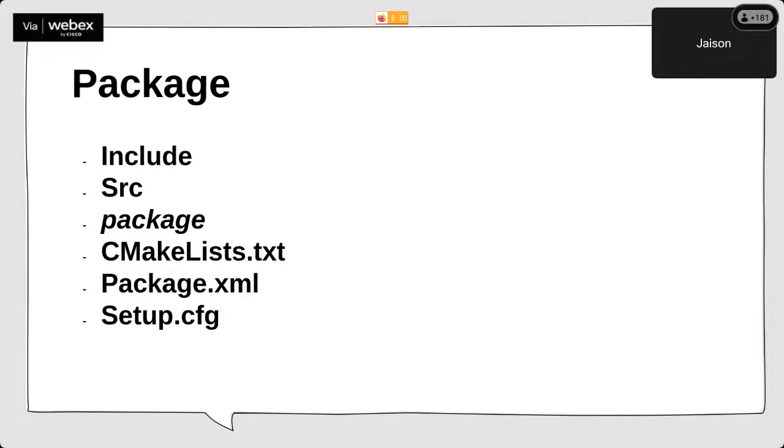So in the SRC folder, you will have all the Python files or the C++ files of how to detect a fruit and all. Then there is also a package. So package will be that same. If you have created a package named perception, you will have again a folder called perception. Inside this is where the final callable file will be. Whenever you call for a particular script to be run, this is where it goes inside the package. So inside the SRC is where you do the changes, but inside the package is where the final callable file will be. Then include is, as you might all know, all the dependencies, all the header files, all the extra files.